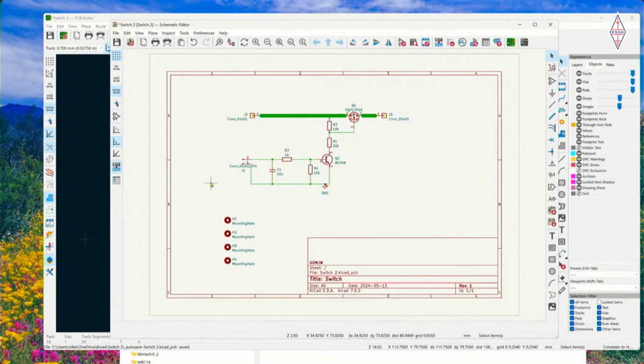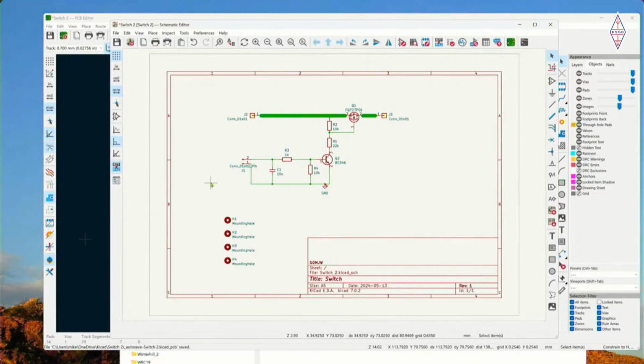Is that a fair summary, Mike? It is, but you could do a bit more than that, because you can't just see if it works, you can see how well it works, so how quickly it'll switch, depending on certain parameters. And you can vary the trigger voltage of the transistor, and you can look for instability. So if you took this switch and, instead of the control pin going, say, 0 to 5 volts or something like that, it went to 2 volts or 2.1 volts with a bit of noise on it, you could then understand what that would do to the output signal, which might be very useful. And it might mean that you think, okay, this simple circuit's not good enough, we need to put a comparator or a Schmitt trigger in there or something like that.